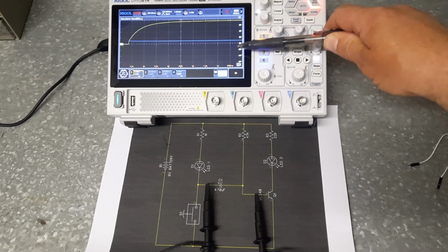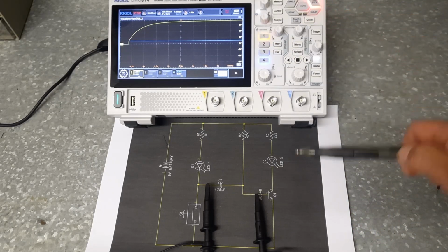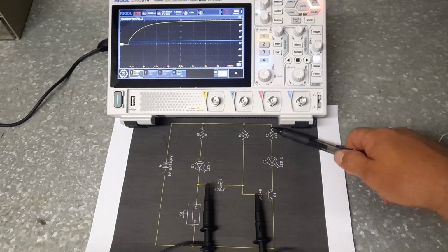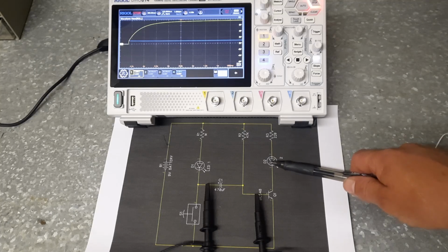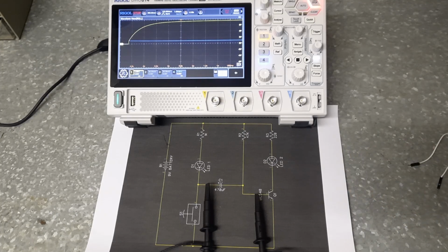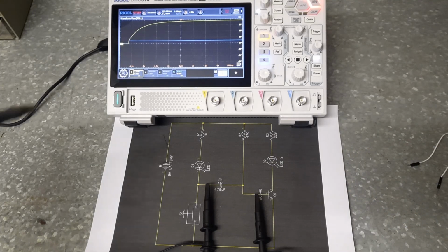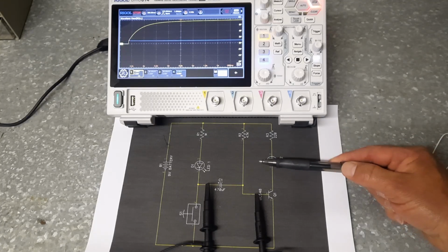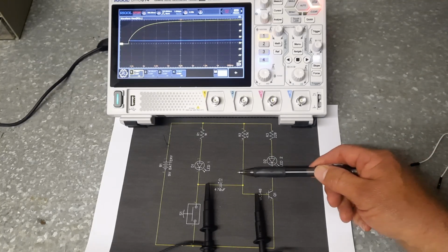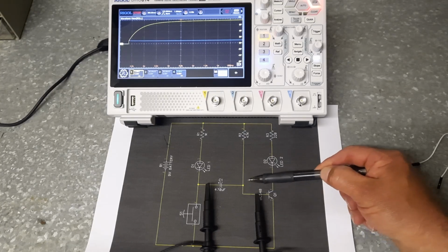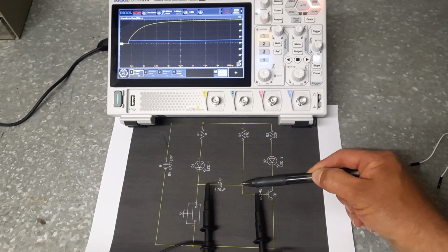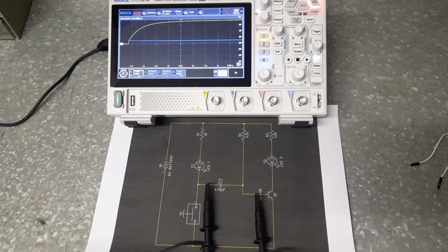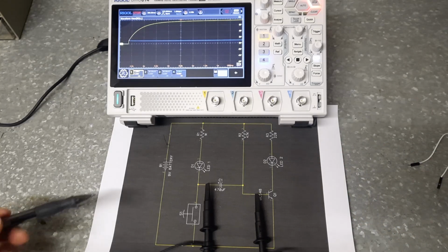While this blue trace is above the 0 point, we know this transistor is saturated, which is why when I first applied power, the LED here lit up. So that's what it shows here. The other thing to be aware of, as I stated before, there is 0.7 of a volt on the negative plate of C1. And that's important.